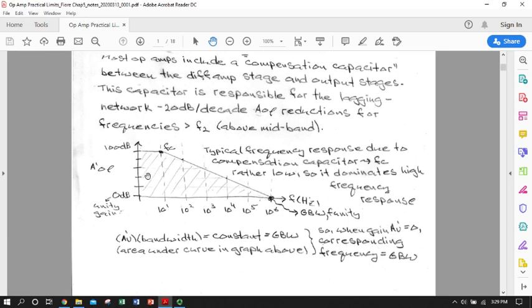So we'd lower the midband down quite a bit, but we wouldn't encounter that roll-off slope until much later. So if we lowered the midband down to say 20 decibels, rather than having an upper critical frequency at 10 hertz, we wouldn't hit it until about 10 to the 4th hertz. But the product of whatever gain we had and the point at which we started to hit that roll-off slope, that product was a constant. And we went over that as part of our derivations of negative feedback advantages.